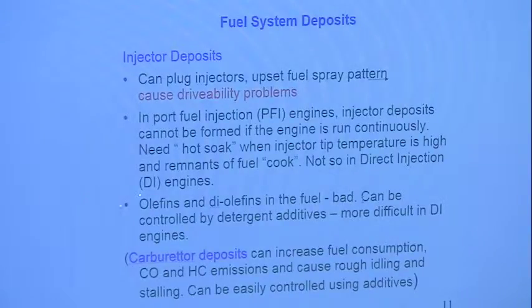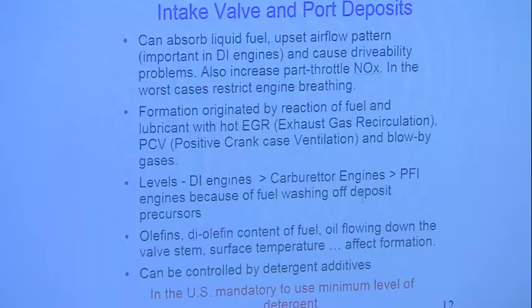In terms of fuels, olefins and diolefins in the fuels are bad for injector deposits. It's particularly so in port fuel injector deposits. But they can be controlled by detergent additives. But this is much more difficult in direct injection engines because the environment in which deposits are formed is different. In direct injection engines, your injector tip is exposed to combustion products in the cylinder, whereas it's much less so in port fuel injection. Of course, we won't talk about carburetor deposits because they're not relevant anymore.